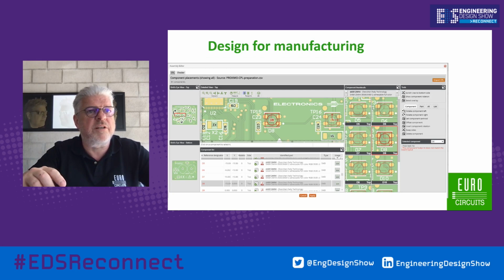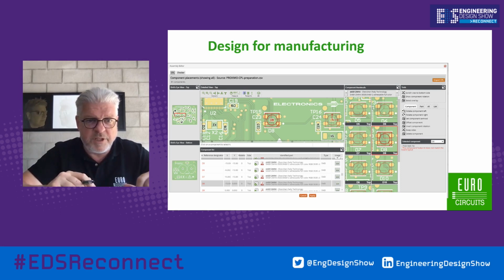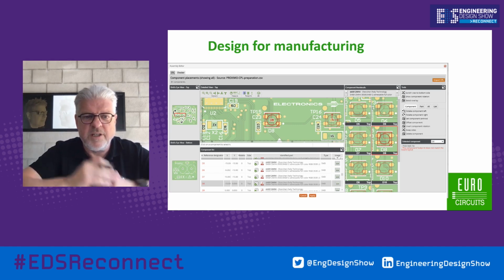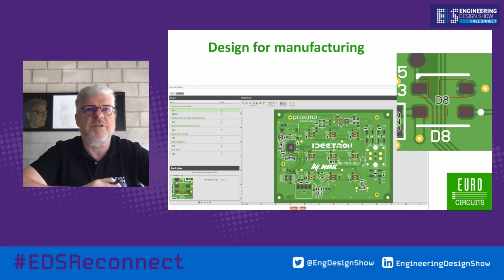Design for manufacturing is a very important thing for looking at PCB and assembly together to avoid mistakes. I think every EMS, electronic manufacturing service provider in the whole world can tell you that every day they meet the problem that they order the PCB from a PCB manufacturer, they order the components from the component manufacturer based on your data, and then everything arrives in logistics. They do a quality check, and before they go into production, they are faced with the fact that the PCB and the component are not matching. So that is a very, very important issue to deal with before you start ordering something.